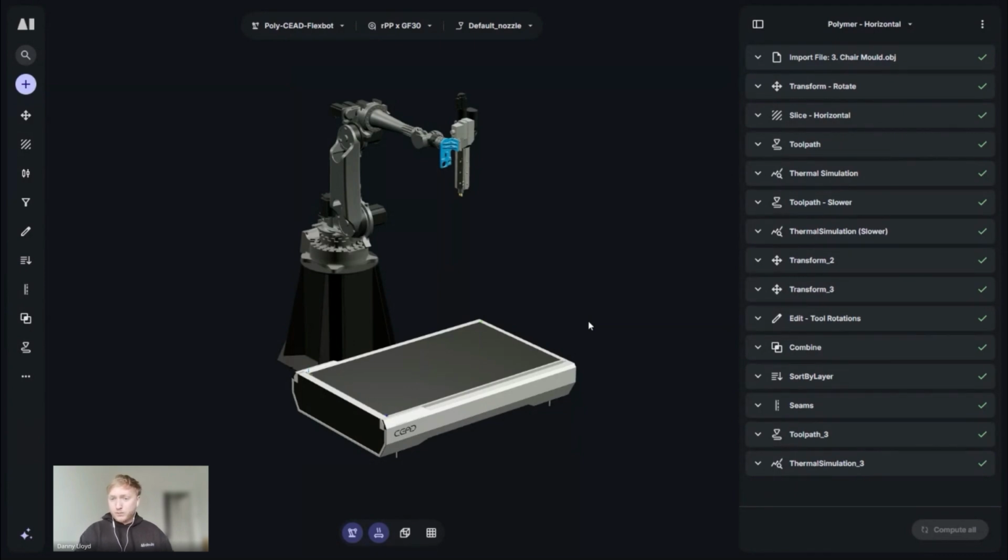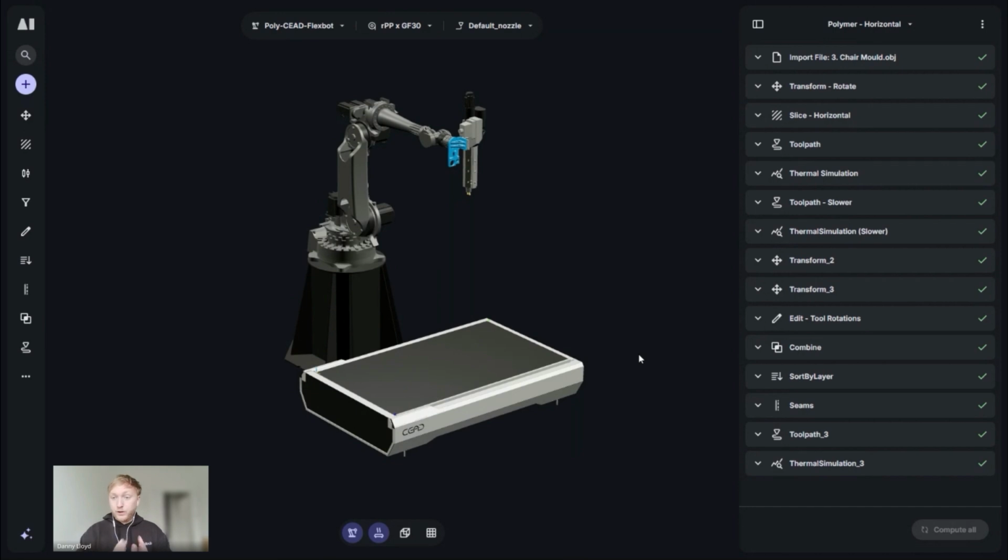That's great for desktop FDM printers and finely tuned and quite highly controlled technology at this stage. For large format 3D printing, for DED, for wire arc additive, for concrete 3D printing, that kind of method isn't too suitable. On the other end of the scale, we've got CAD CAM type solutions. They are absolutely fantastic for CNC, for milling. They're not as finely tuned for additive manufacturing, and they can be quite difficult to use, quite long to create toolpaths, and like I say, they're not really set up for additive manufacturing. Whereas Aibuild sits somewhere in the middle.